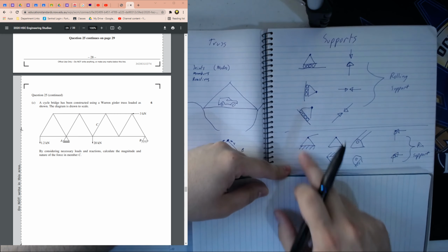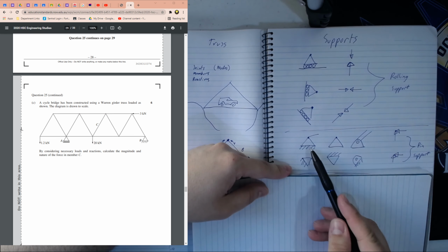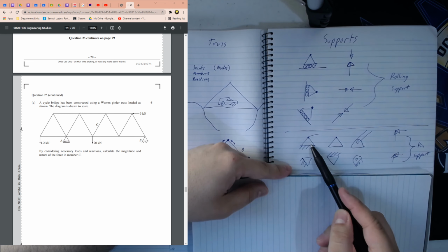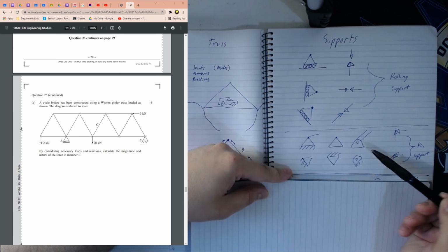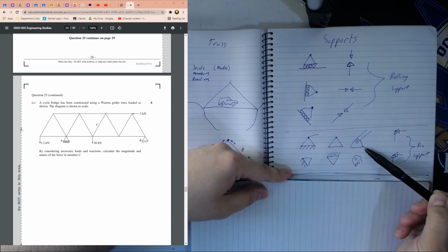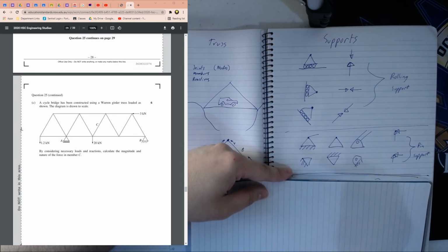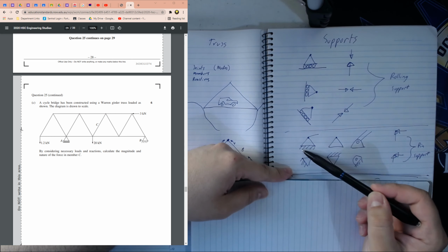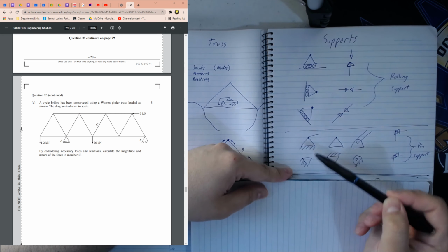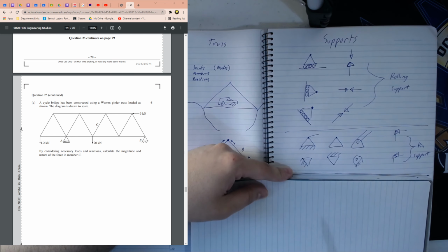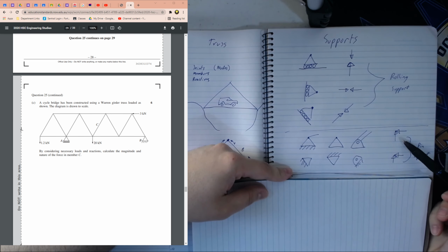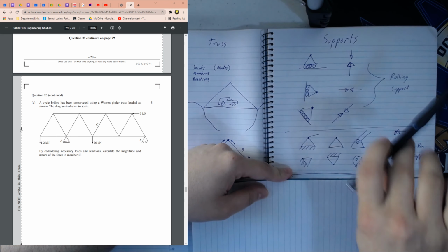These are all examples of pin joints. This one over here looks a lot like our point B in our HSC example, but it can be in all directions. Sometimes they can be graphically drawn like this, or like this. The key thing to look for is if you see any of these lines, that means it's connected to the surface. That's a dead giveaway that this is a pin joint. It's not moving. Pin joints can provide forces in the vertical and horizontal. They actually provide forces in all of the X and Y directions, so any angle.